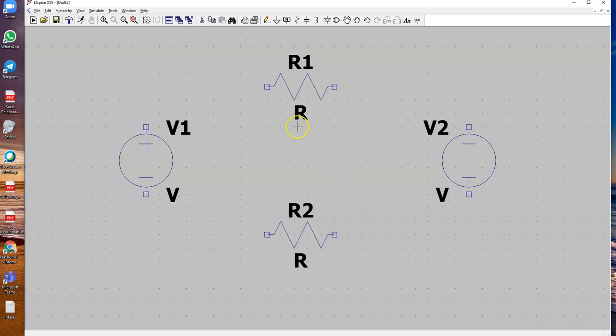Right, now you can connect all these components here by using the wire here. Let's connect there. Or you can just go through the elements, because LTspice will not be connecting those two terminals of the elements, but rather it will bypass the elements. Okay, so you just press that, and then you can go through the elements here, and then finally connect to the negative of V1. Alright, so we have a complete circuit here.